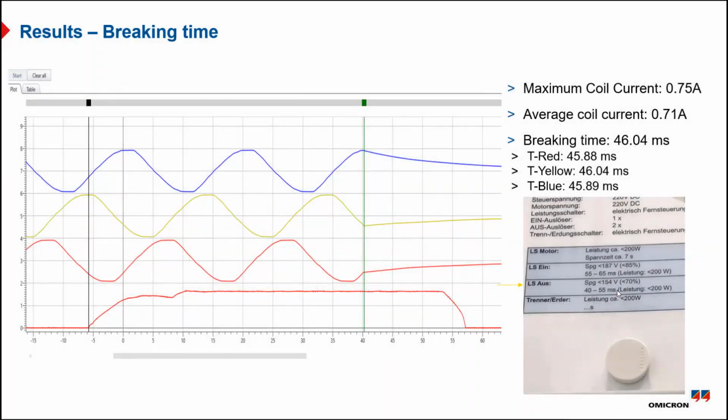When I did the measurement, you can see there was a very clear sine wave, and once the breaker opened, the voltage started decaying in the capacitor. So it will take some time for the voltage to become zero. We are not expecting the voltages to become zero for doing our measurement. We can start doing our measurement when the